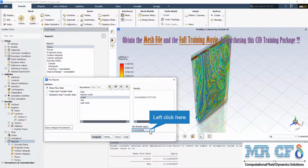Finally, we can check the mass flow rate from the outlet boundaries. The magnitude is negative because it is a mass flow outlet, and we see the effect of buoyancy flow, which leads to the air going outside from the facade chamber. With this mechanism we can have a good ventilation system, and it's also a passive ventilation system.